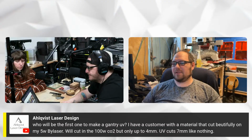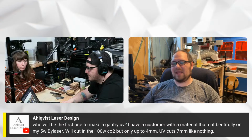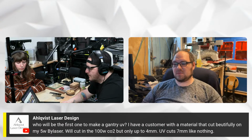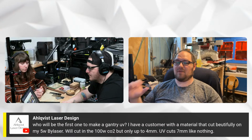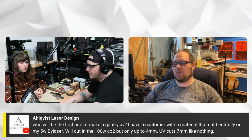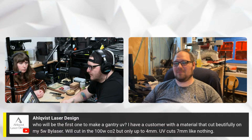So it would probably be infinitely cheaper for you to get like a 150 watt CO2 with an assist gas and a 4-inch lens, and you would probably have a far easier time. I don't know what you're trying to cut, but if it cuts with the 100 watt and you can do 4mm, you'll probably have an easier time with a 4-inch lens, so you have a longer focal range and add more power. And I mean, a 150 watt replacement tube is like 3 times the cost of a 100 watt replacement tube. So there's a downside to that, but it's still going to be cheaper by probably an order of magnitude.